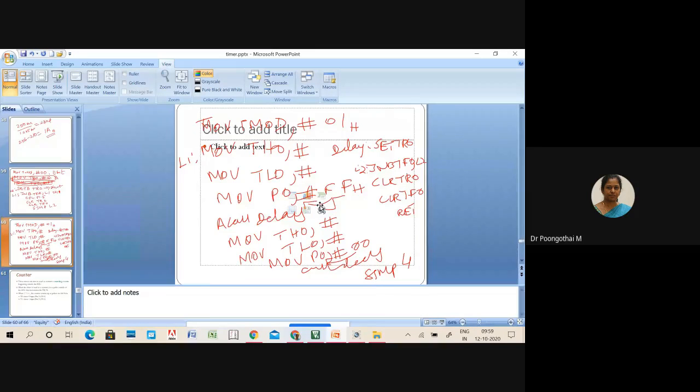Please tell me. Before calling the delay function, we can set a carry for on time purpose. And for off time purpose, we will clear the carry. In the delay function, we will call jump-no-carry and the corresponding initial values will be placed. Please write the code. I will go through that.